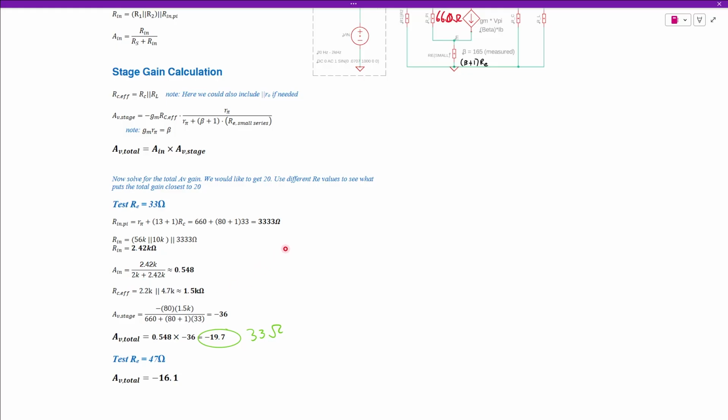In most situations, they'll run through the problem and they don't have a source resistance, so your gain works out great. And then in real life, you actually use this and it doesn't work out. In fact, it's actually half. So we'd be getting negative 10 if everything was ideal. We don't want that, so we're taking it into account.